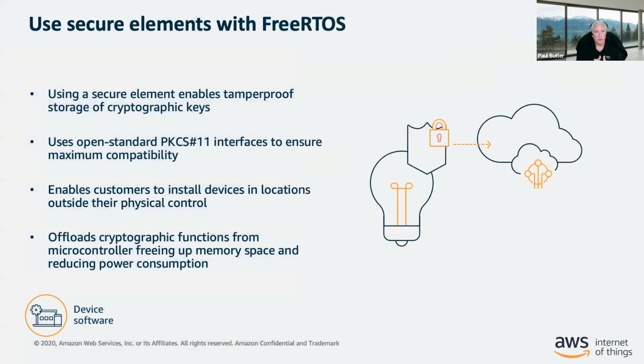Okay, and then I wanted to talk a little bit about secure elements. Secure elements are another hardware device that are typically soldered onto your board next to the microcontroller, and there's a standards library called PKCS 11 that is an API interface to talk to these secure elements.